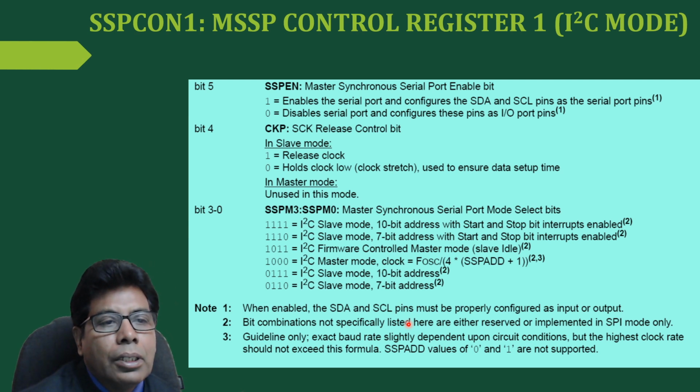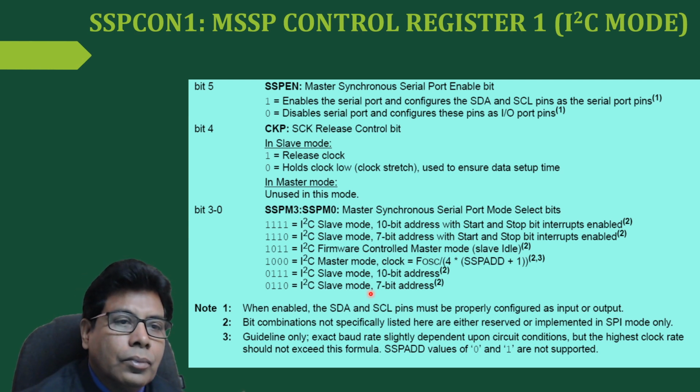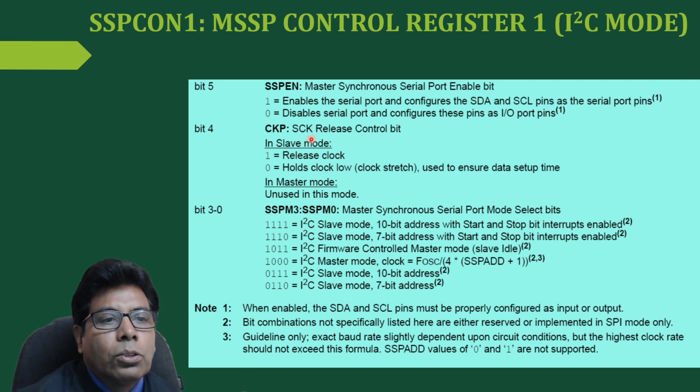Then bit 4 is the SCK release control bit. So in slave mode, 1 means it will release the clock and 0 means it will hold the clock.